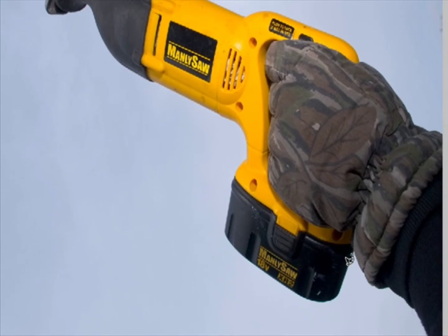5. Click in the image to set the first fastening point. Fastening points anchor the selection border in place. 6. To draw a freehand segment, either release or keep the mouse button depressed, and then move the pointer along the edge you want to trace. The most recent segment of the selection border remains active.